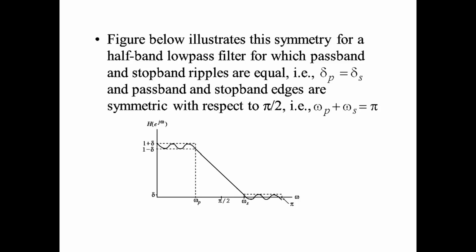What is the advantage of having zeros in the impulse response? When the coefficient values of these filters are zero, and certain input comes, when these filters are multiplied with the incoming input values, they will result in zero. So computationally, it is very attractive to have zeros in the impulse response.